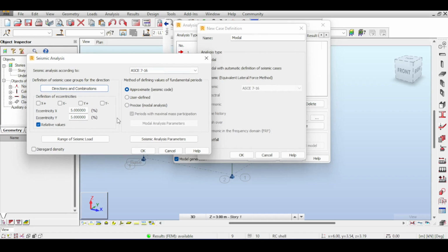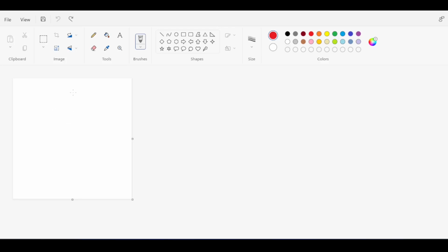So before I continue, I want to explain to you why earthquakes cause loads. The idea of seismic loads is basically according to Newton's laws. So if you have a mass M, let's say, then there is a mutual relationship between the force and the acceleration, meaning if you apply a force, then an acceleration is imminent. And if there is an acceleration, then there must be a force that caused it, be it inertial forces or external forces.